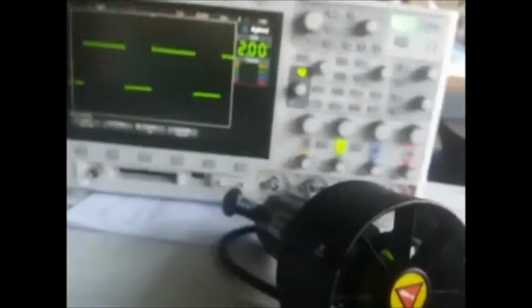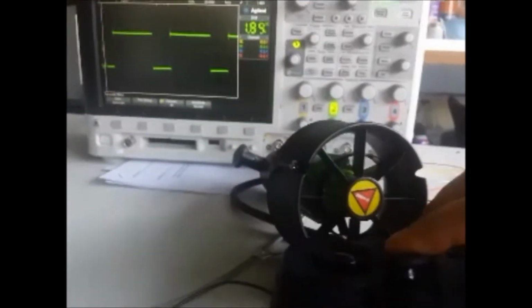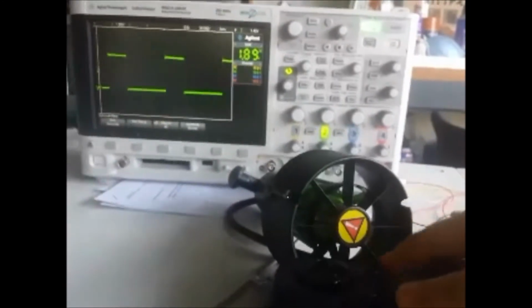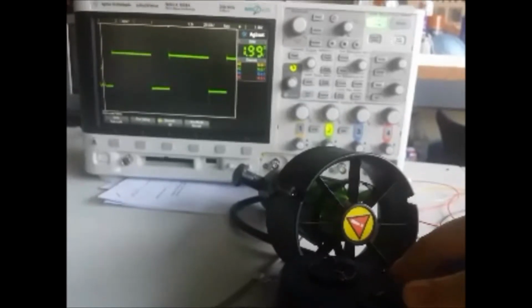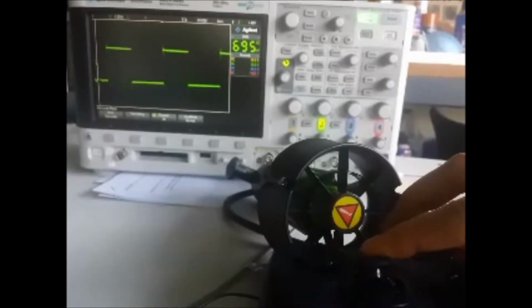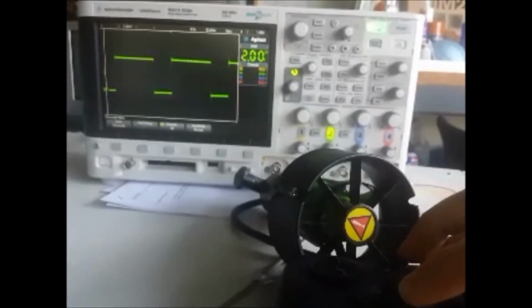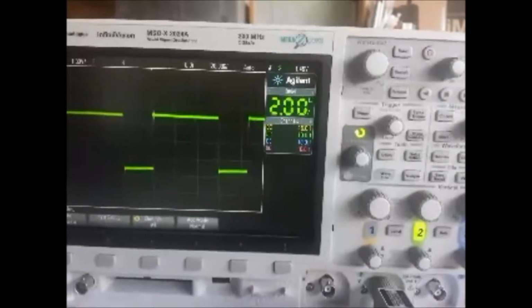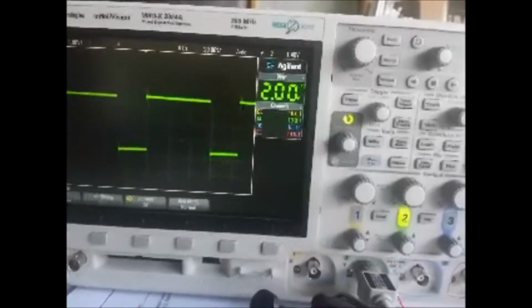In the background, I set up an oscilloscope that shows you the duty cycle. If I ramp forward, you can see it slowly ramping up. Notice there's no jerk. And then I go in reverse fast, and you can see it ramp down slowly. You can see the number in the background right there. That is the actual pulse width modulation, the voltage that I'm emitting out of the microcontroller.